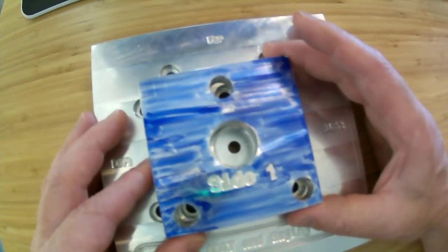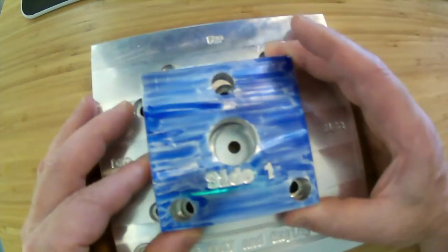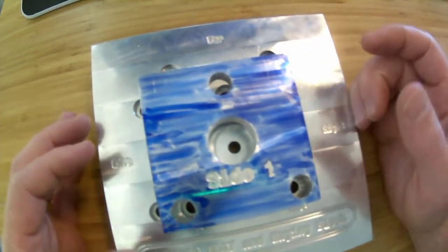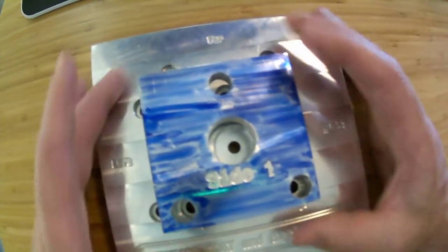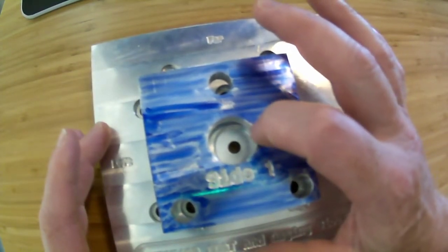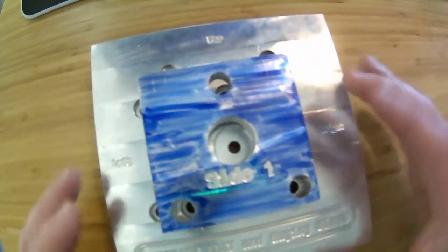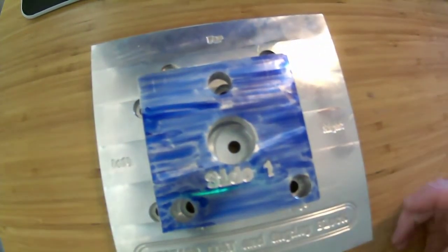Now, you'll note that it can also translate in the positive Z direction up towards the camera, but remember, we have an assumption that after we have put these locators in, we're going to put a clamp, or maybe a couple clamps, on here to hold it down against the locators. Okay, so then we need to put something in the next direction.